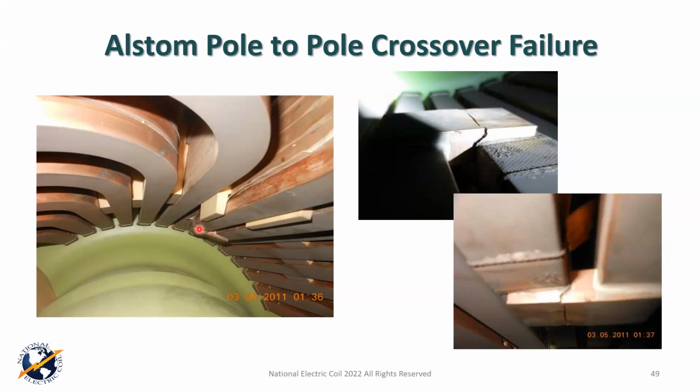When I said the coil moves less up here, I didn't say it didn't move at all, but it moves less. If I handed each of you a piece of copper that's 1/4 of an inch thick and 1 1/4 inches wide and any length you want, how many of you could stretch it about 3/16 of an inch? That's what you'd have to be able to do to avoid this cracking. So not a good design.